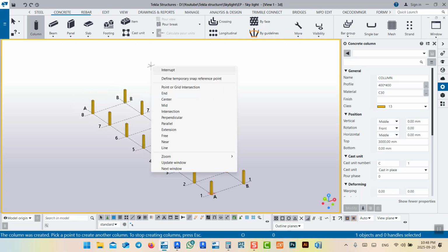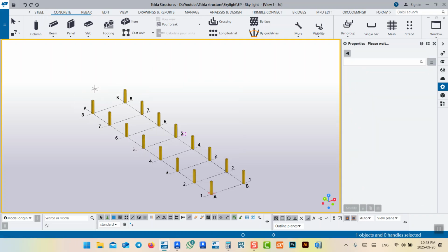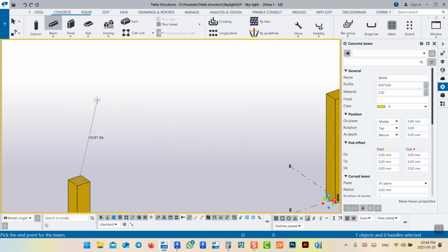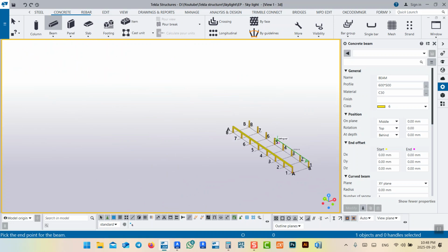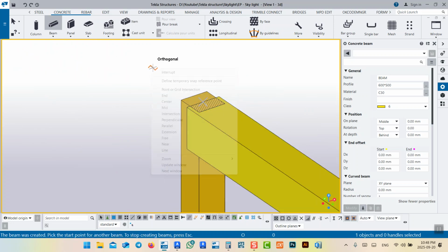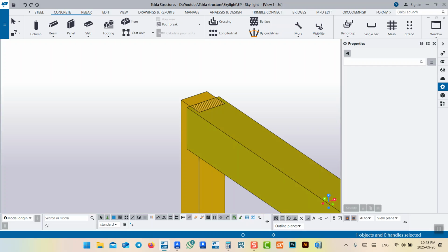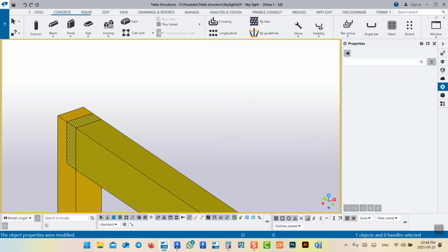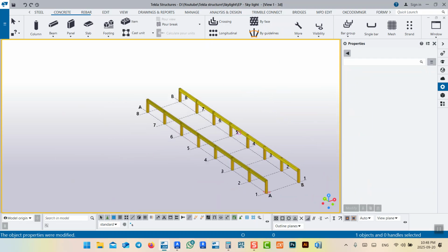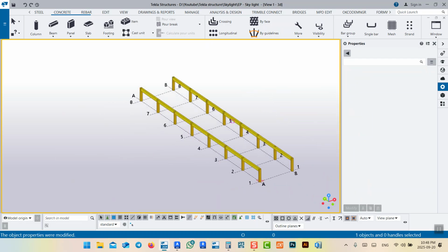just like this. And after that, of course, we have beams. So I will make a longitudinal beam, and from this side also. After that, I'll specify the height, good, and I want to make the width 40 so as to fit with the column. Okay, now I have modeled the concrete structure.